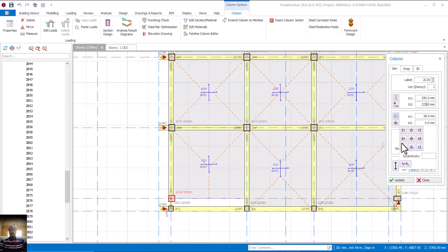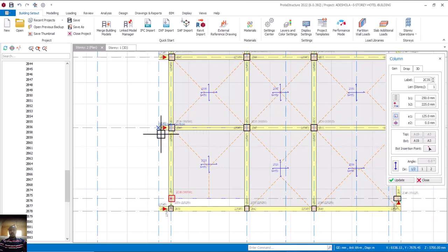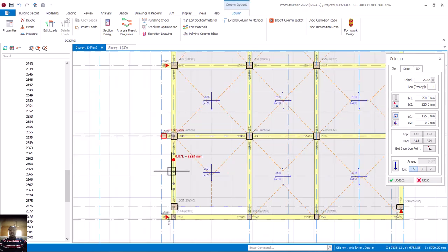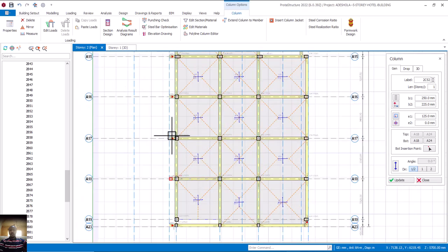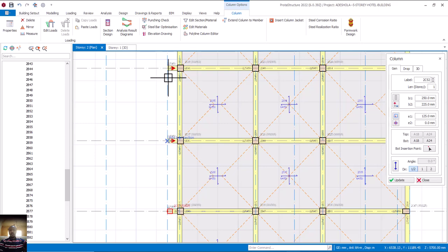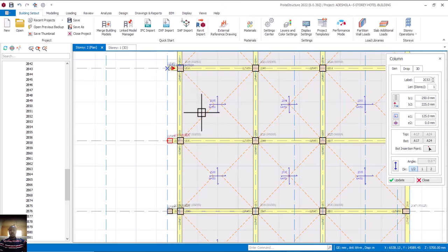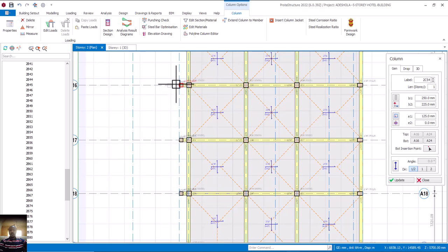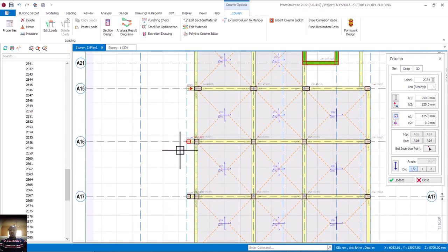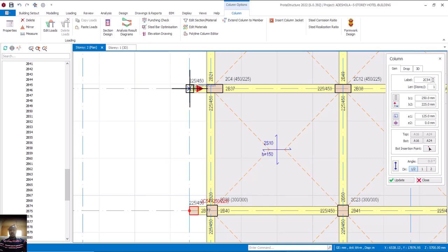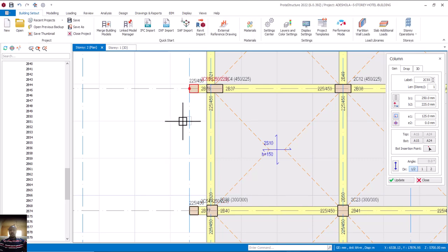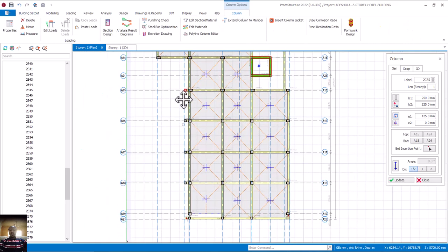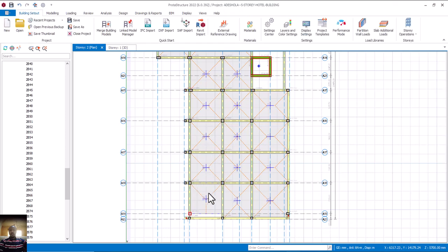Let me come to this place and change the pattern. Is it correct along that line? Okay, it's okay. So I'll come to this place also and put it here. You can now see that this helped me to know that at the ground floor I'm having this beam here. So I don't need to be going down and coming up to see where my cantilever beam is. So that is that. Then come to this place also.